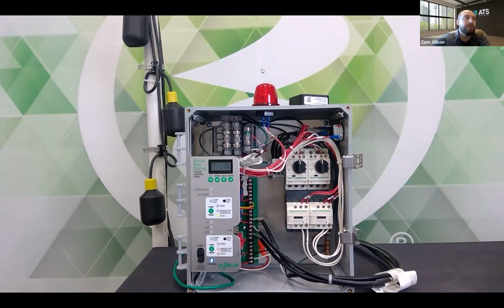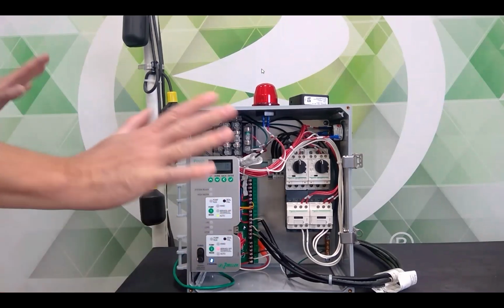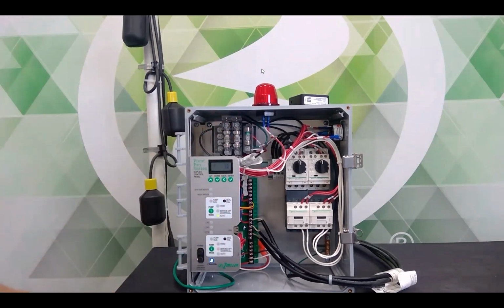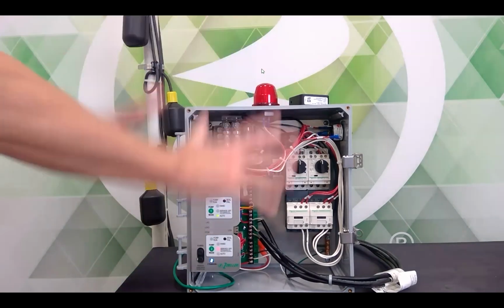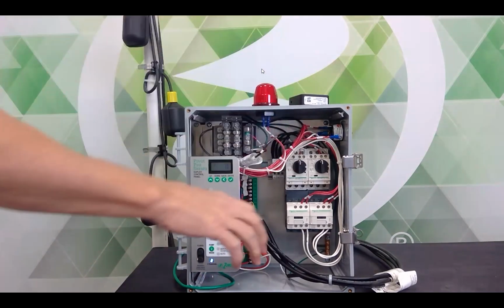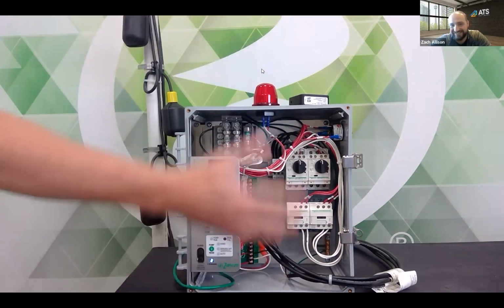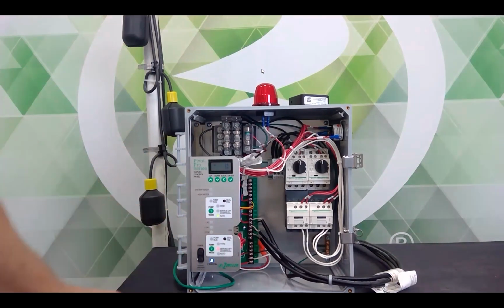So if 10 years from now, 5 years from now, there's an issue in a pump and they need to take it out of the station and replace it, they press and hold that button, lift up the pump, replace it, and drop in the new one, and you're still going to at least have a simplex operating. That's right. But just to be careful, and I'm sure a couple engineers are already screaming at their screens, you're going to power this all down before you get into the pit. Of course. Let's be clear about that. But when you power it back up, yes, you would just put it into simplex by doing that.